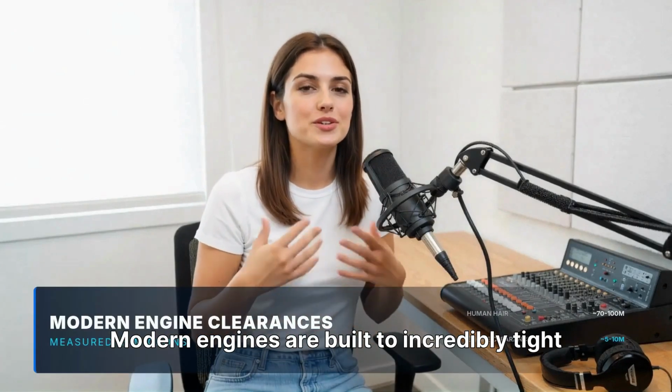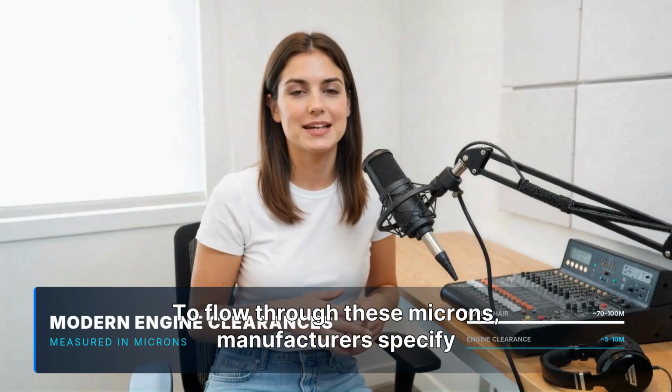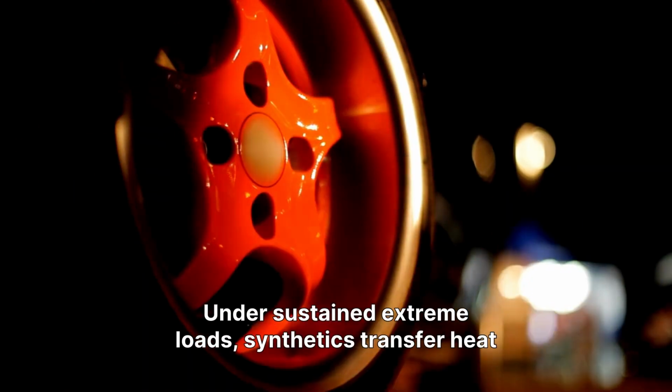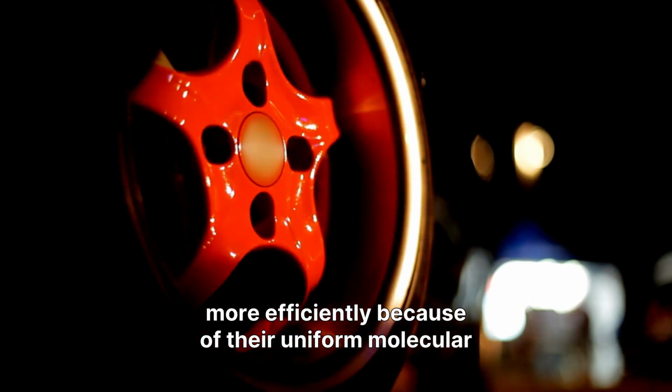Modern engines are built to incredibly tight tolerances. To flow through these microns, manufacturers specify very thin oils. It is physically impossible to make a stable 0W20 out of conventional mineral oil. You must use synthetics to achieve that cold flow. Under sustained extreme loads, synthetics transfer heat more efficiently because of their uniform molecular structure.